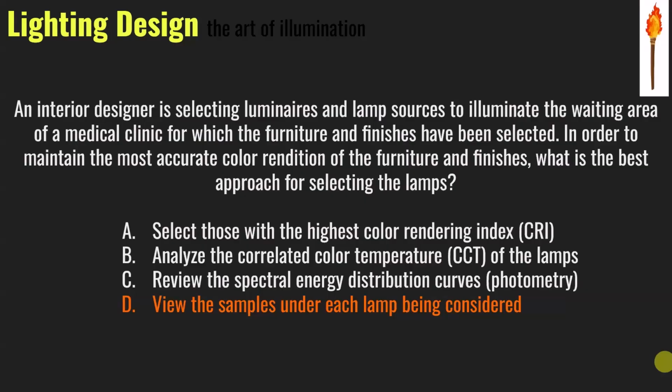Color rendering index. Yes, it goes from 0 to 100. There are some newer technologies that argue, but it's hard to know with the color palettes that are being tested with, that they are over 100, which 100 is what the sun is. Theoretically, we can't achieve sunlight and nothing is up to 100, but most LEDs, if they're of any good quality at all, are above 90. They're 90 plus. Okay. A lot of them will be like 93 or 96. So they're all very good.